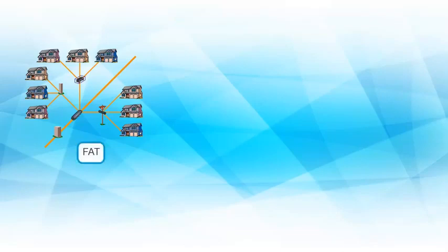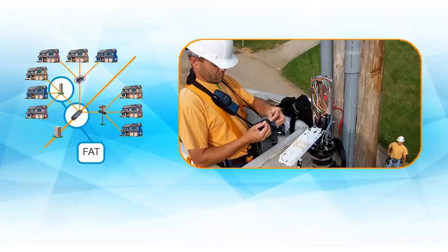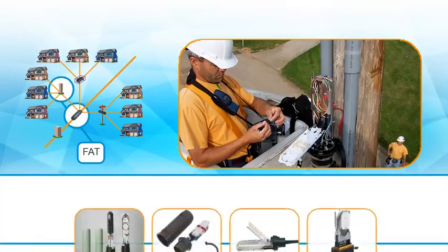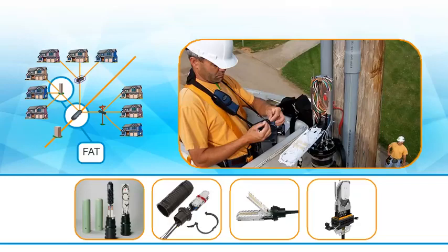These are called fiber access terminals, FAT, and can be splice closures or hardened connector solutions. In the FAT, distribution cables are spliced to the individual fibers or fiber pairs of the drop cables, and these units are usually positioned at an optimum or strategic point within the network, enabling the drop cabling to be split out as close as possible to the majority of subscribers.